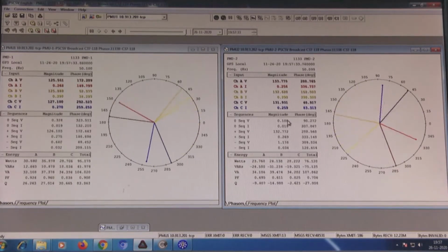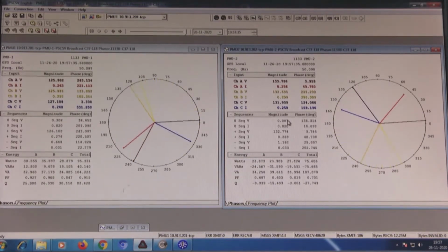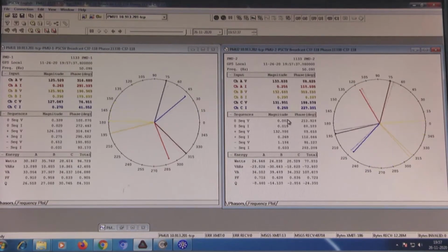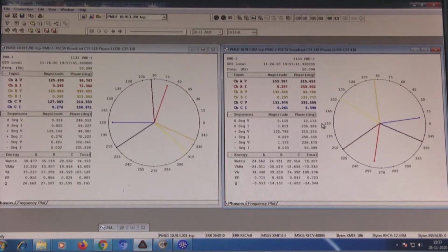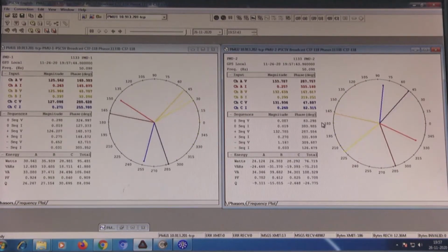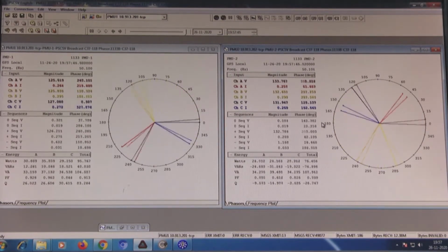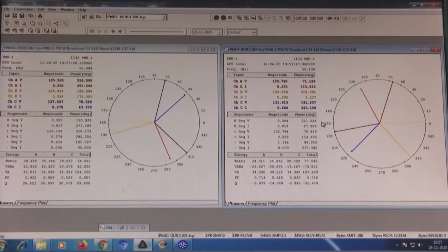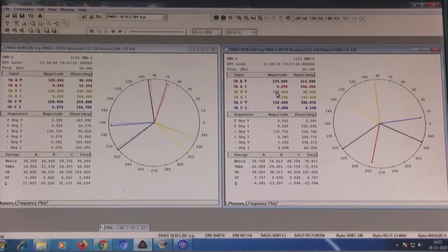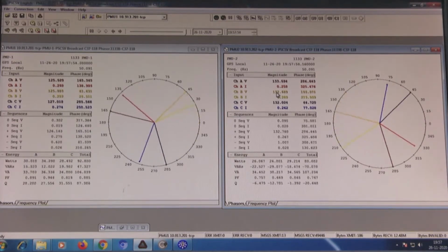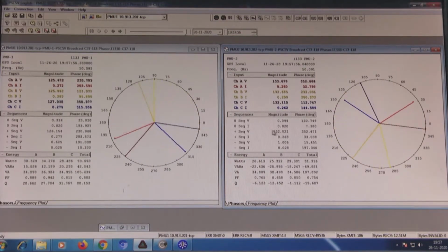Now, what happens is that this line is connected from both these sides. So, if you see here also, the grid side voltage being higher gives the charging current to the system. Therefore, the current is leading in this case, and the current amount is much smaller because of the limited capacity of the system. So, therefore, we observe the system behaviour like this.